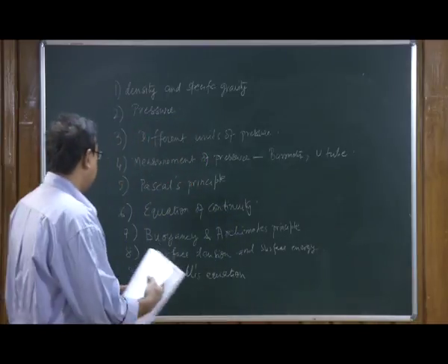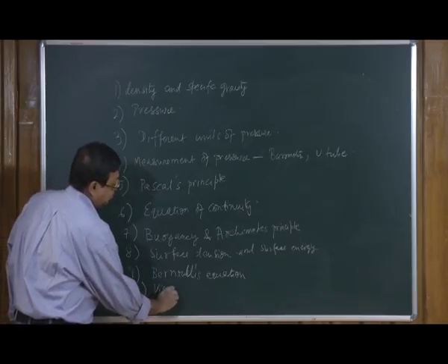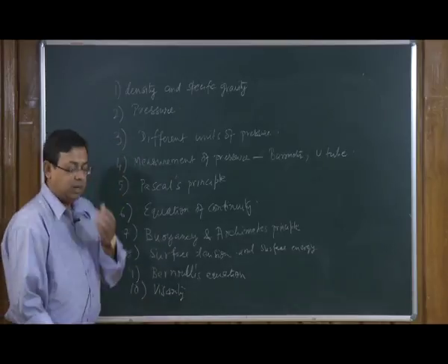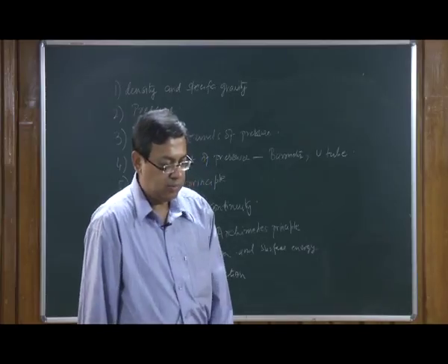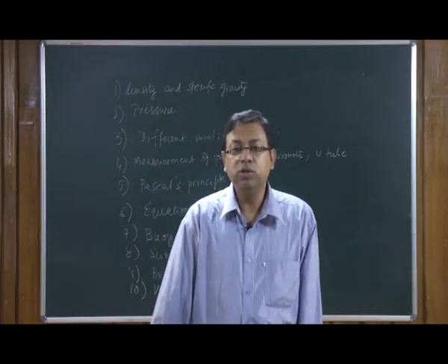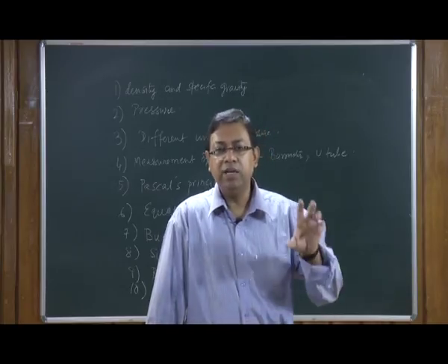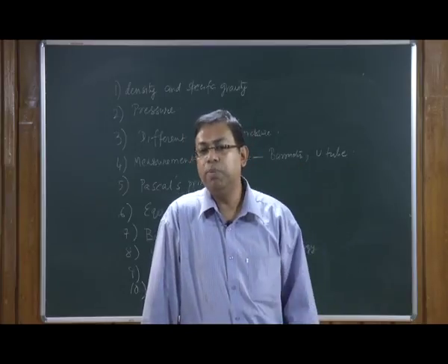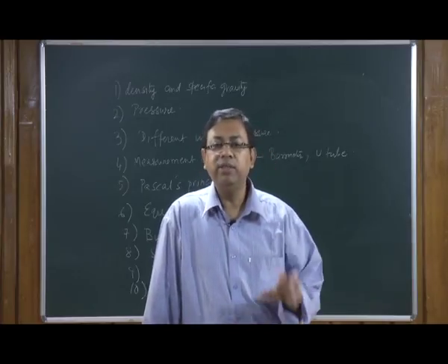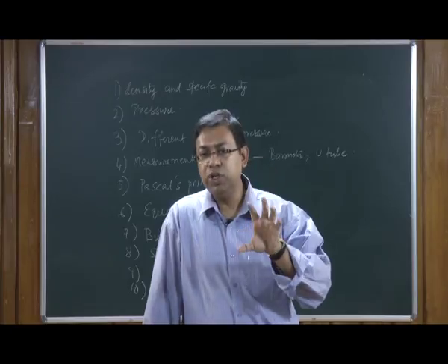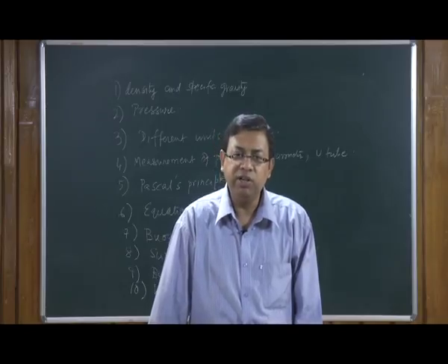And finally, we have looked at viscosity, a property of the fluid because of which different layers of the fluid move with different velocities. For flow through a pipe, the central lamina moves with a greater speed, with the speed going to 0 for the layer in contact with the inner periphery of the pipe.